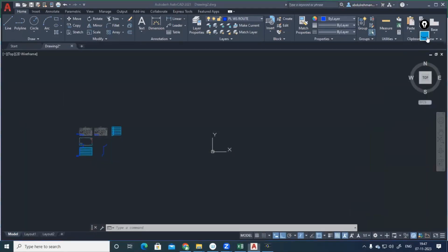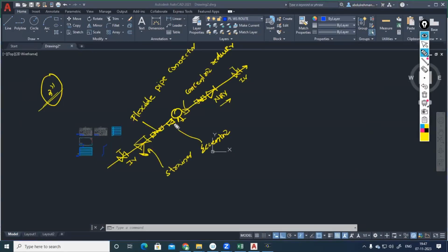In most cases this will come reversed, meaning the manufacturer's pump inlet will be less than our requirement. Less than, so a reducer piece will come, but that will be eccentric. Why are we proposing this eccentric reducer on the suction side?